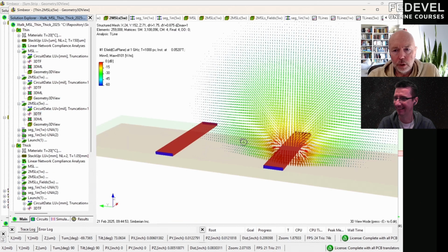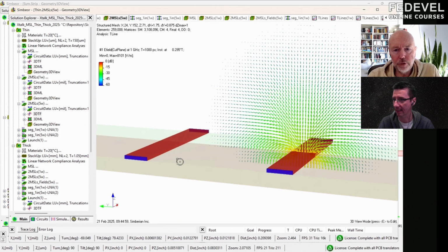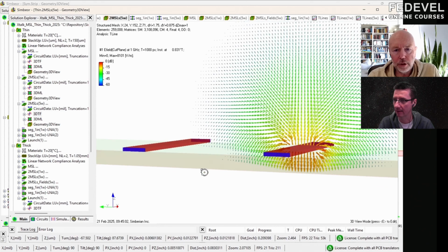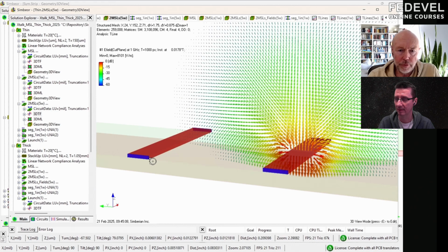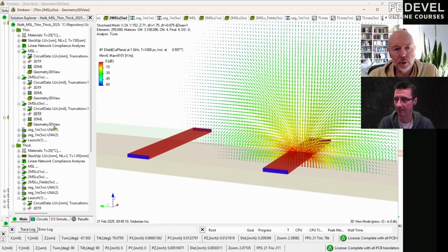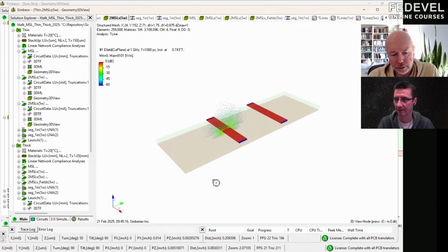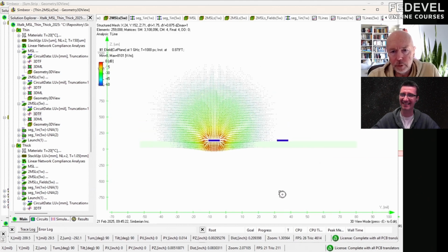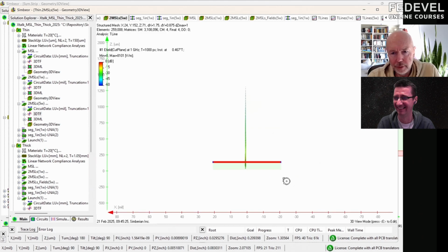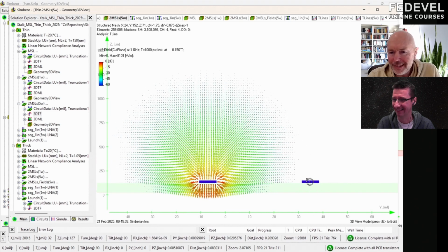Okay, so let's first see this and explain what we see. So this is 5W between the tracks, in the thin stack up. You can see that the thickness of traces is about the same in both examples, but right here they look thicker because of the whole scale of it. Let me just switch the view. The field doesn't even reach there. Okay, like this. Yeah, you can see that it still reaches a little bit.